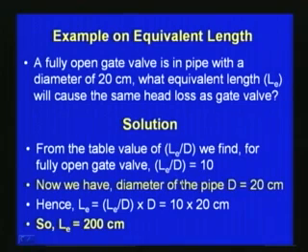So for the pipe system, like this we can solve various examples and problems wherever various fittings are there. We can find out what kind of fitting it is, and then the LE by D values are known. So once the diameter is known, we can calculate the equivalent length.